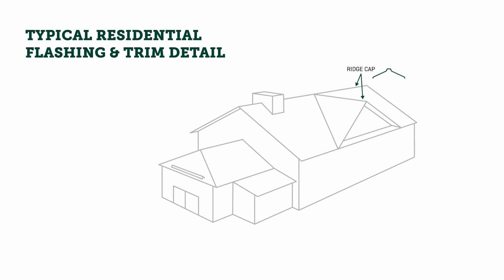The ridge is probably the easiest one to identify. It is simply where two ascending slopes meet at a level horizontal peak. While hips are similar, they occur when two descending slopes run perpendicularly away from each other and meet at a diagonal plane. Valleys essentially have the same description as hips, although they have two descending slopes that run into each other and meet at a diagonal plane.